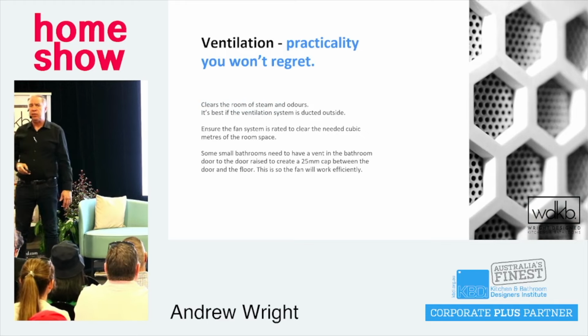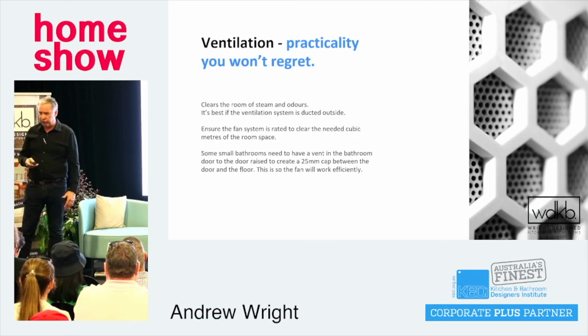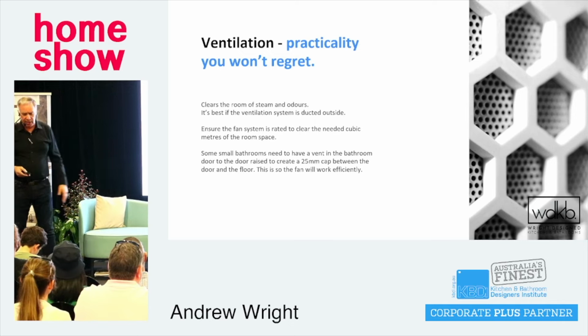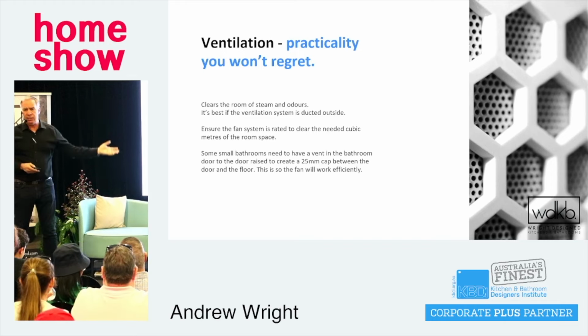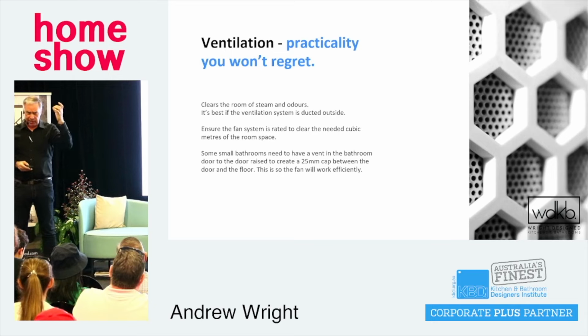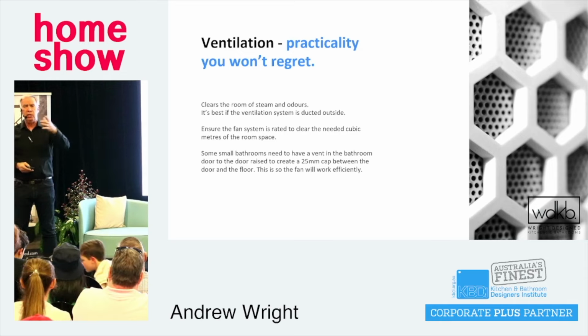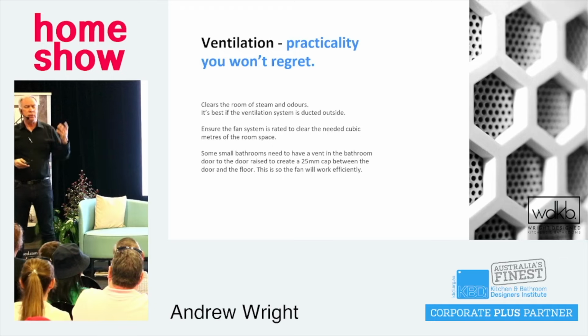Ventilation is something that a lot of people kind of have as an afterthought during the bathroom renovation. A lot of people have Tastic lamps and that sort of thing. But whatever ventilation you have, particularly a ceiling fan, it must be ducted outside. You don't want to put all the moisture into your ceiling, onto your insulation. You don't want to short your lights out or your wiring circuit with steam. So you must have it ducted outside.